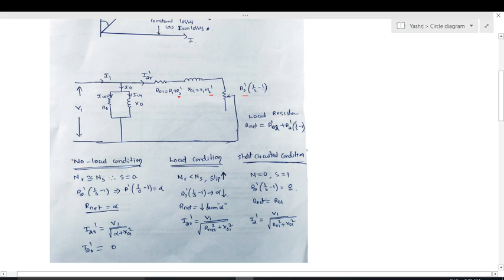First of all, yesterday I discussed the no load condition. Now, how the net resistance, the total value of the resistor, behaves under no load, under load, and under short circuit or blocked rotor test. R01 is R1 plus R2 dash plus R2 dash into (1 by s minus 1).